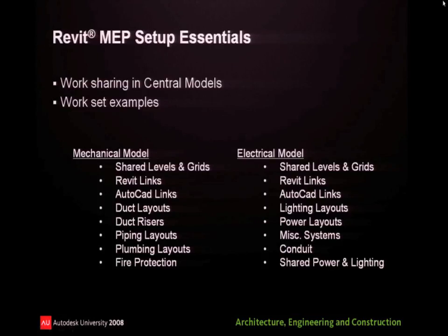Duct layouts and duct risers. Revit MEP has systems which butt heads with work sets, as most of us who have worked with Revit MEP may know. What we have done to try to get around some of that, we've created a separate work set for risers and a separate work set for third floor ductwork, second floor ductwork, first floor ductwork. If that riser's on a separate work set, we tend to have fewer work sharing issues when, say, we've got an air handler that serves all 3 floors. Someone's working on the third floor duct system. If someone else is working on the first floor duct system and they're trying to connect to the same system, we have less propensity for work sharing conflicts.